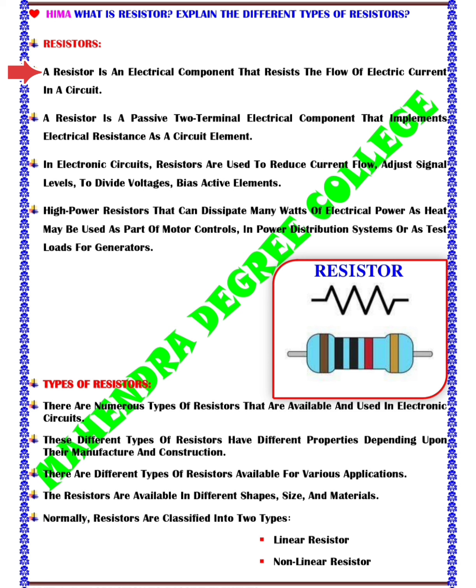Resistors are used for many purposes. A few examples include limiting electric current, voltage division, heat generation, matching and loading circuits, gain control, and setting time constants. They are commercially available with resistance values over a range of more than 9 orders of magnitude. They can be used as electric brakes to dissipate kinetic energy from trains, or be smaller than a square millimeter for electronics. High-power resistors can be used as motor controls and in power distribution systems.